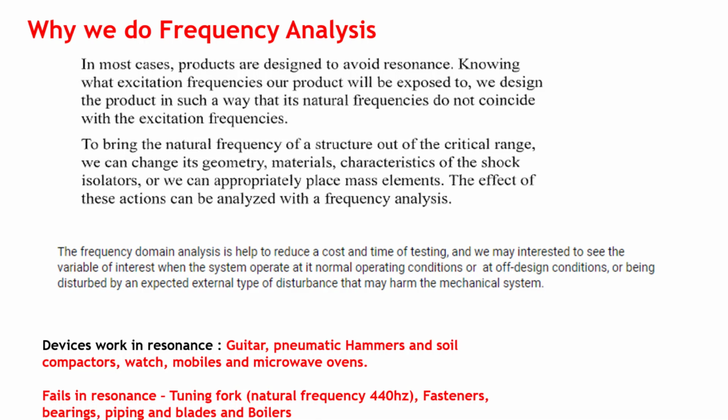We can design these components in such a way that their natural frequencies do not coincide with the excitation frequencies. To do that, we can change the geometry, change the material, or even add dampers.